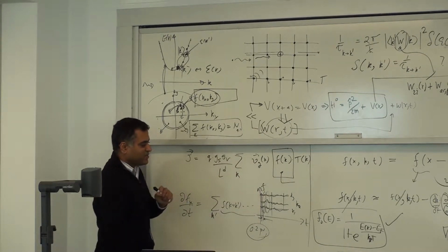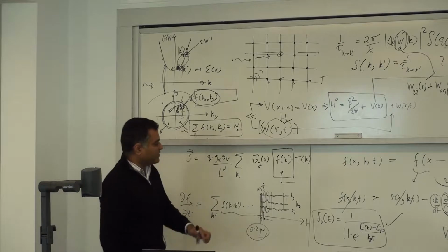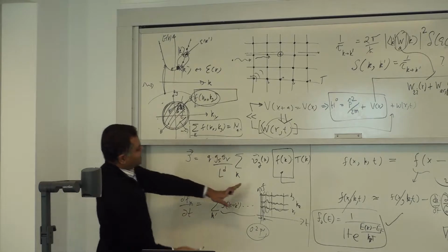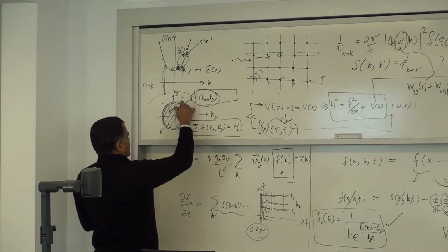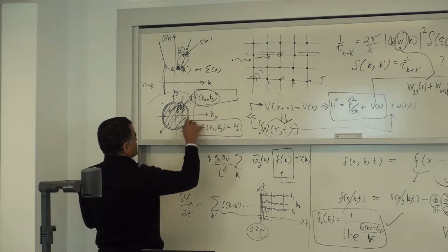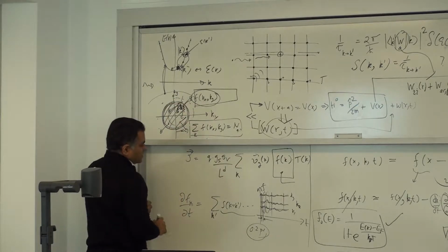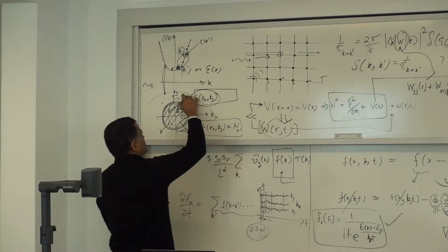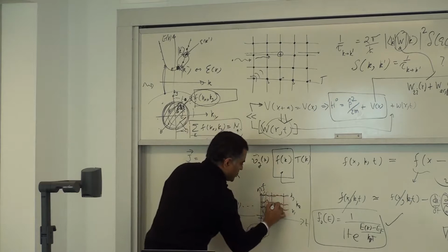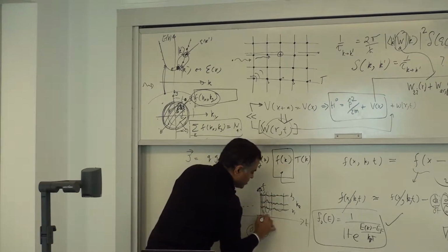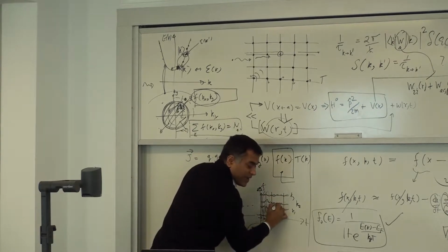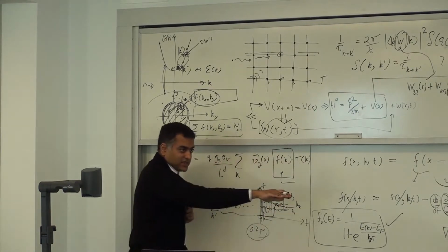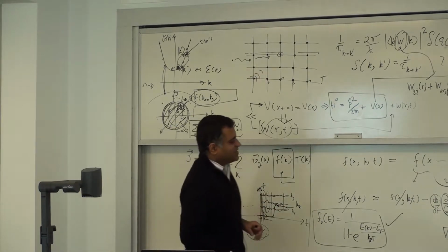And that I can do very easily by applying an electric field, right? My Fermi-Dirac distribution was like that, and that was equilibrium steady state. Now I apply an electric field, and maybe I have more carriers going to the right, a little less going to the left. But given enough time, that also reaches steady state, right? So if I'm tracking the state here, that state occupation function maybe was very low, and then it went up, and then it'll maybe oscillate, do something, but it'll reach steady state again, right? So equilibrium and steady state are slightly different.